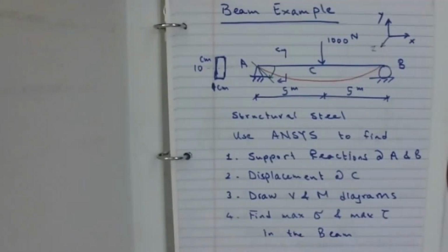But once I start a new project, I am going to define a static structural analysis. So I double click. The first item, engineering data, we do not have to do anything because we're going to use the default structural steel. Second step is to go to the geometry and I'm going to right click to launch Design Modeler. So I'm going to say new Design Modeler geometry.